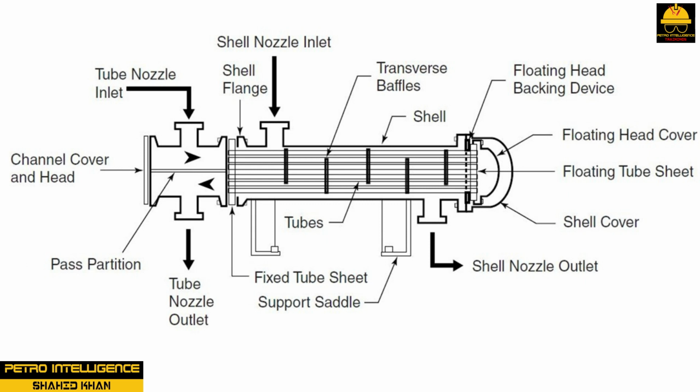A network of baffles is established on the tube bundle to enhance heat transfer. Adding fins to the tubes can further enhance heat transfer. An impingement baffle or pass partition is located between the tubes and shell inlet. This redirects the flow and keeps the tubes from being damaged. This type of heat exchanger produces the highest heat transfer efficiency. Floating head exchangers, with their high cross-sectional areas or fins, are designed for high temperature differentials and high flow rates.